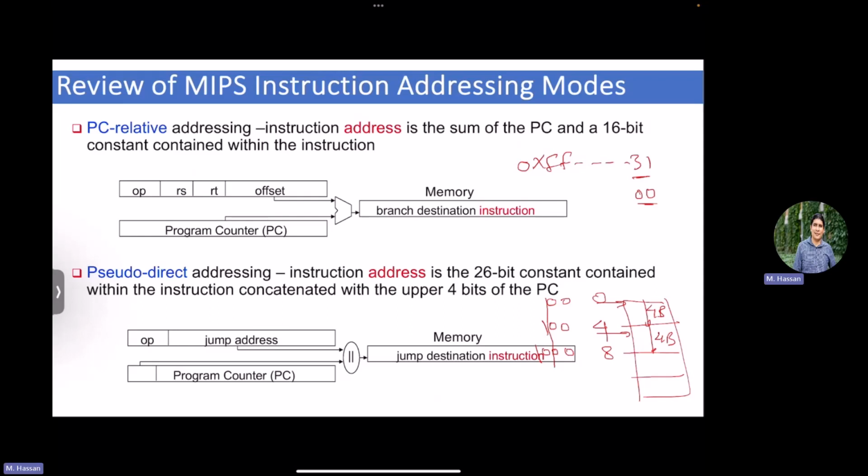Okay, so some of the principles, again, to revisit them to conclude that topic. This not only maps a general RISC, fixed size instructions to simplify stuff. Here we're saying simplicity favors regularity. Why is regularity very important? Because if you have a very regular behavior, you can optimize your hardware to accelerate the operation of this regular behavior, right? So you have fixed width instructions. You have a small number of instruction formats. We said earlier when we started this topic, the smaller number of formats you have, the easier for the decode unit to basically differentiate between them, right? So the logic is easier.